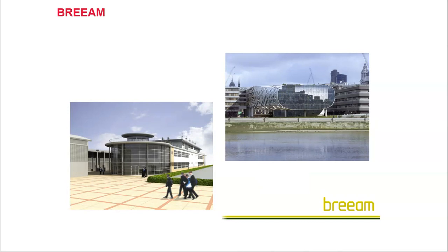Delivery time is certain or more accurate, and then installation time is more accurate. But the problem is, if you're working in the US and pursuing LEED, you're not getting any certification or points if you're using prefab construction. In fact, you are minimizing all the waste generated at the site, and all the airborne dust and everything that can occur during construction on the site by using prefab.